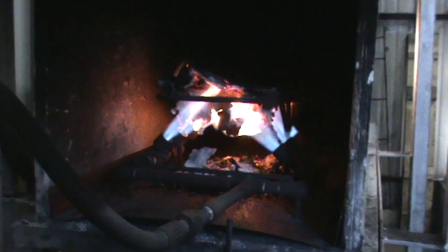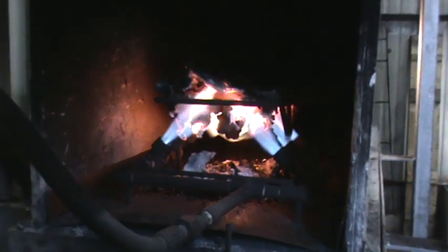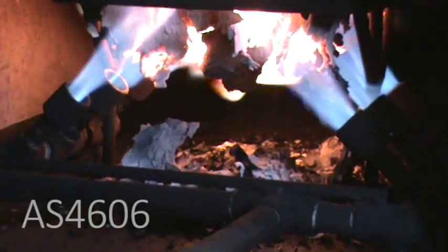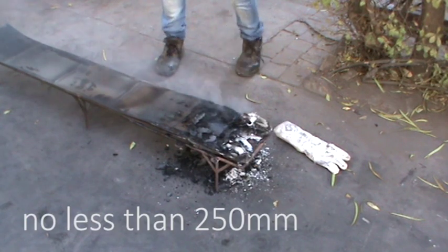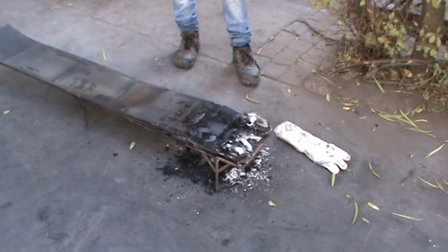G. Gallery test. To determine how much a flame will propagate along a belt once it has caught fire can be determined using a gallery test apparatus. The results of this test are determined by measuring the amount of sample belting left undamaged once it has been removed from the flame, and therefore this is in units of millimetres. The requirement, as per AS 4606 standard, is that there should be no less than 250 millimetres of a 2-metre belt sample left undamaged as a result of the burn test.